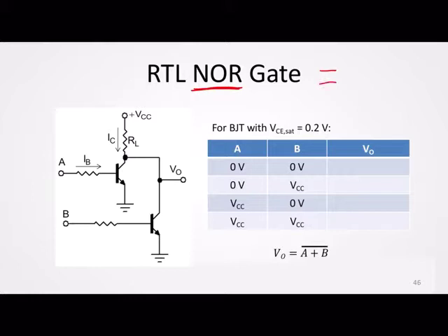If you recall, I mentioned last time, a NOR gate, which is drawn this way, is just equal to an OR gate with an inverter. So it's just inverting the logic of the OR gate. That's the schematic symbol, and we represent it in equation form as this equation here. So the V out in this circuit is A or B and then inverted. So that's the NOR gate.